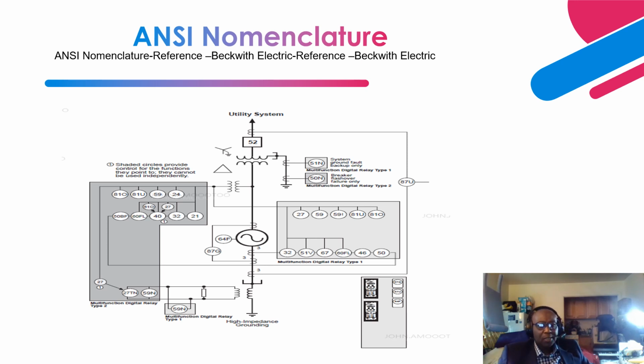Next is a typical setup of the generator protection elements for a typical power plant. All right, so as you can see over here, this is the connected utility system. So the AC grid is on this side, right? This is the unit breaker, and its ANSI nomenclature is 52. So anytime you use the word 52, then we know that you're talking about a breaker or a unit breaker.